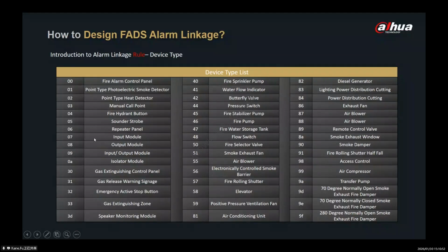So when the fire alarm triggers in the smoke detector below the module, it will report to the system as a smoke detector fire alarm, like that. And also for some input modules that you want to use for monitoring elevators or some other kinds of systems, you need to redefine them following the list. Okay, that is the structure.